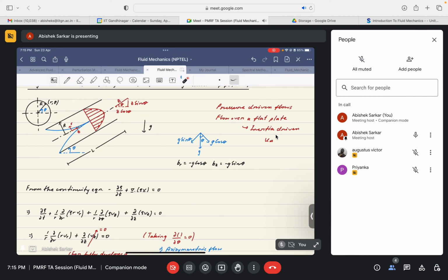So in the developing region, the velocity profile is a function of both x and y. Okay, I won't say x and y since we are using cylindrical coordinates, so let's be consistent with our coordinate system. Let's say I use r and z. That would be much better. So while the flow flows through this developing region, the velocity profile changes at different z locations. Basically the velocity profile here would be slightly different than the velocity profile some distance away from the initial z coordinate.